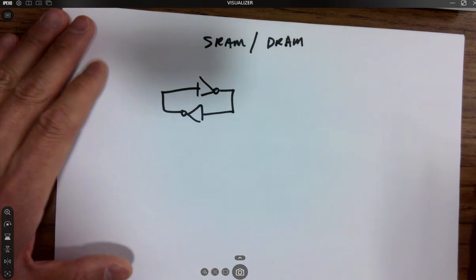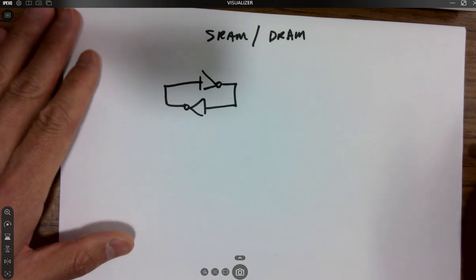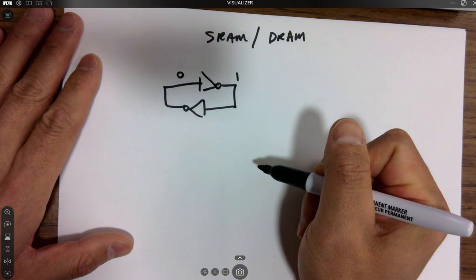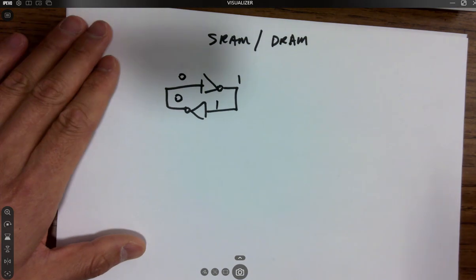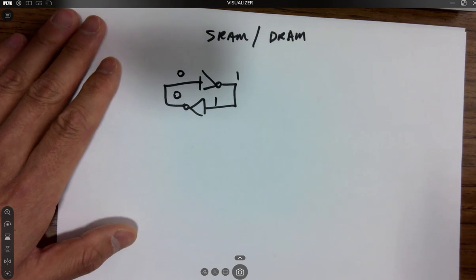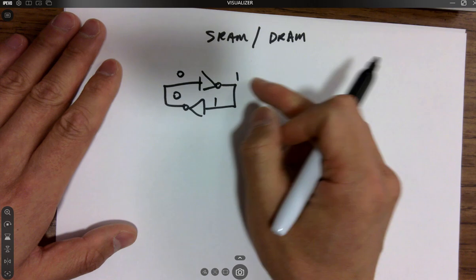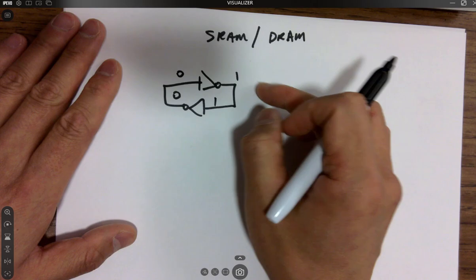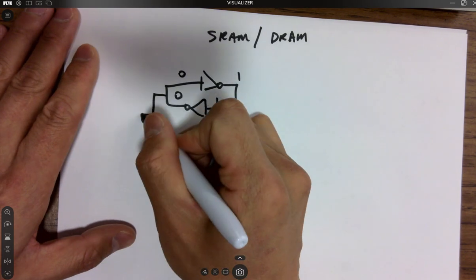it's a latch like this. So why is it called a latch? Yeah, 0, 1, right? And 1, 0. Stable. What if you add another inverter here? Put three inverters in a ring. What's that called? Ring oscillator. Yeah, it's going to oscillate, right?